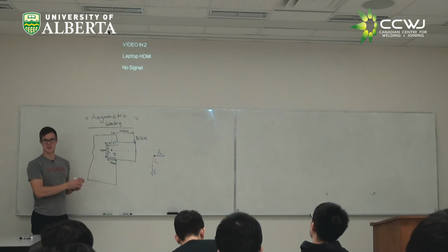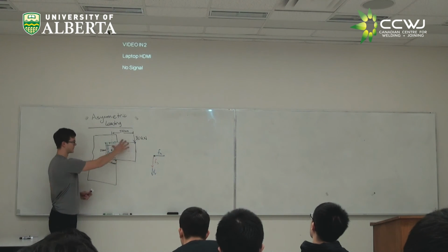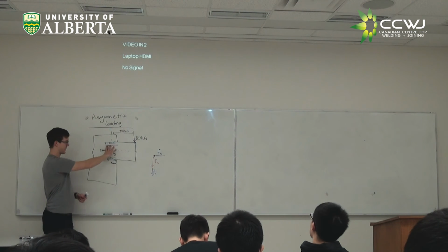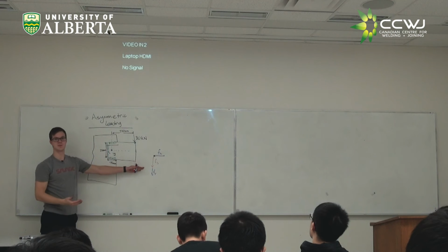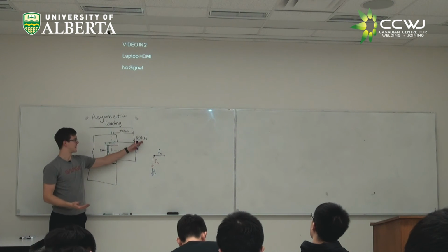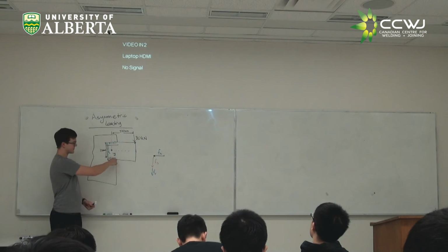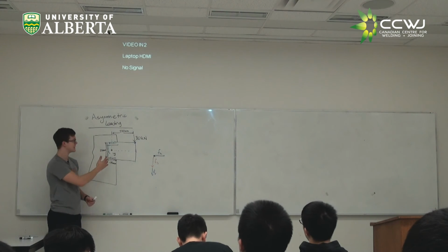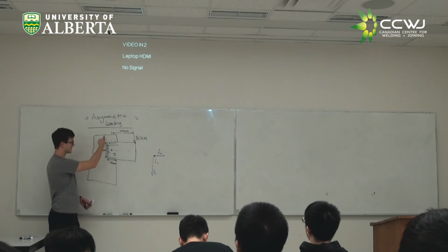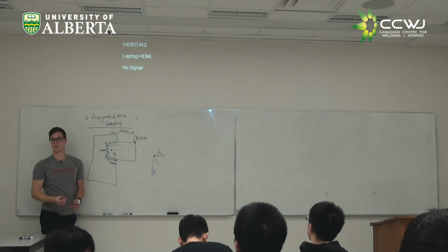These equations were given in today's class. If you have a load for a situation where it's a bending acting at some distance from the center of gravity, you're always going to have these three components. You're going to have some horizontal force that develops in your welds, some vertical force that develops in your welds, and some shear force because of the load that's in line with them.